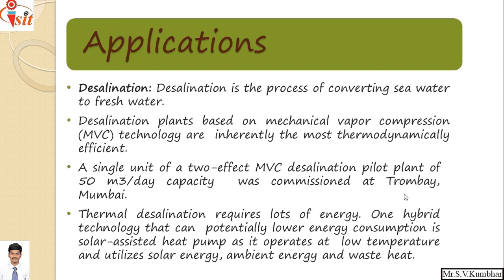Desalination of seawater. Desalination is the process of converting seawater to fresh drinkable water. Desalination plants based on mechanical vapor compression refrigeration systems are inherently the most thermodynamically efficient. Thermal desalination requires a lot of energy. One hybrid technology with potentially lower energy consumption is the solar assisted heat pump, which operates at low temperature and utilizes solar energy, ambient energy and waste heat, so that salt water can be converted to fresh water which is used for drinking purposes.